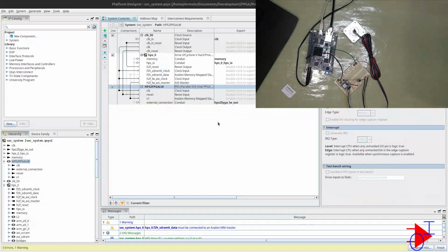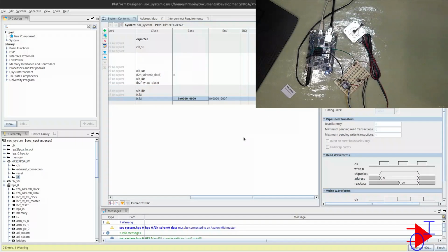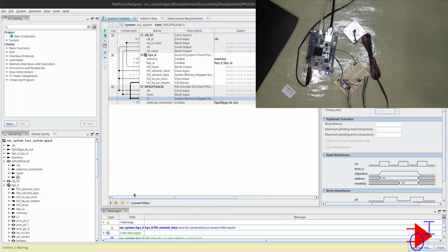Once the HPS writes, we will increment, let's say after every 5 seconds or every 2 seconds, to the next number and the next number all the way up to 15 and then back to 0. That's what the program is going to do, and it will validate the working state of the read and write process through this lightweight memory location.